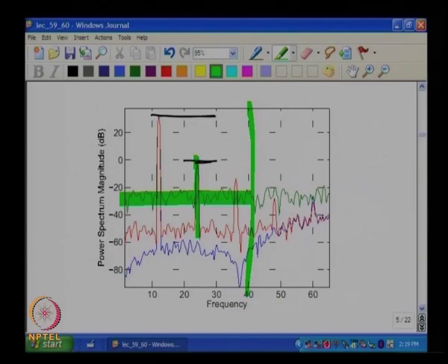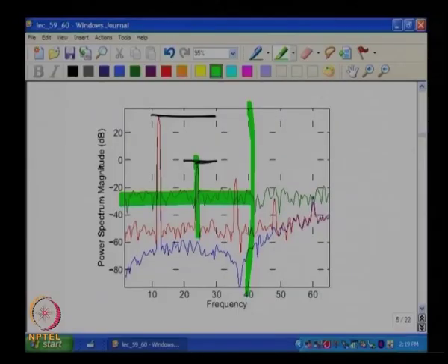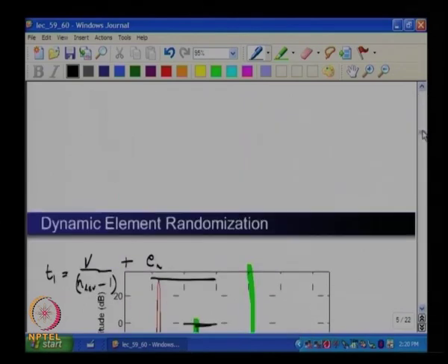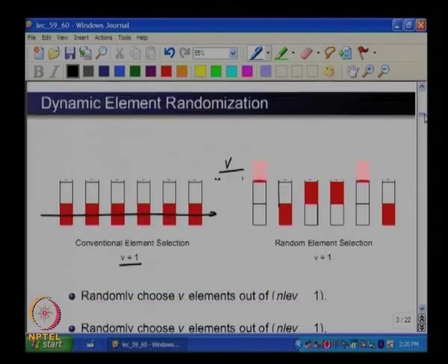Now, you start to get greedy and say, all I am doing is generating each thermometer drive waveform to be V by n level minus 1 plus some other error sequence, correct. You understand? Please note that each thermometer drive waveform now is a 2 level waveform, right.